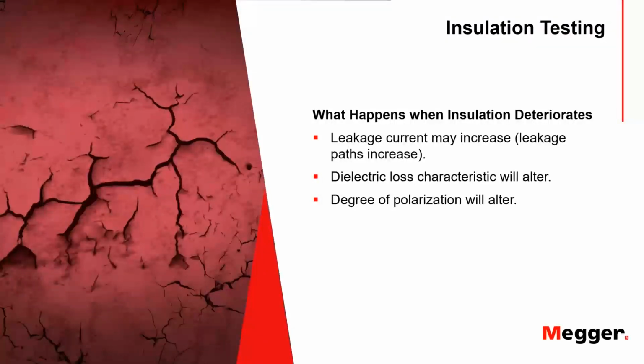And the main thing we're going to talk about a lot here today is the nature of insulation breakdown. Modern materials are huge organic polymers that are all linked together. And as the insulation ages, those polymers start to break down. You get what is called polarization.